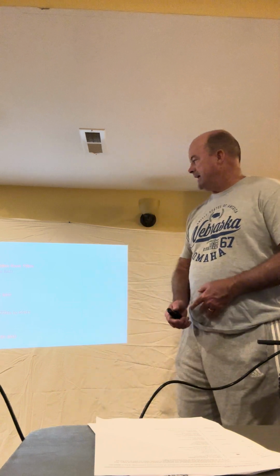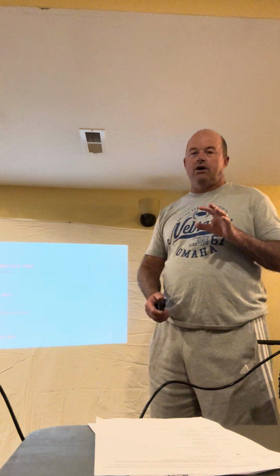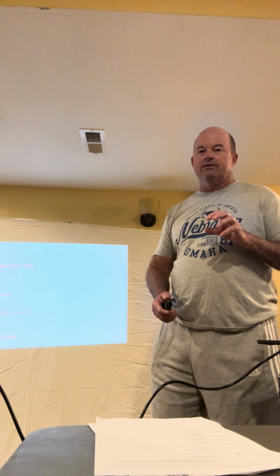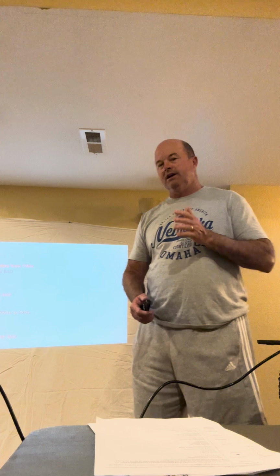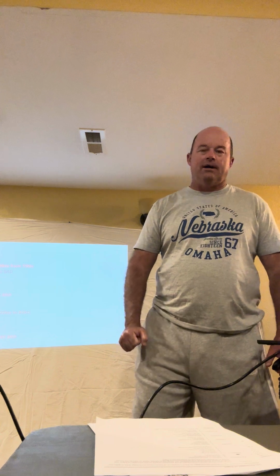When you come to land, if you get into a stall, right, it's very difficult. A lot of people die because they've got aft CG and they can't recover from a stall. It makes it much more difficult, right? It's kind of like a tail stall. So that's how you want to think about that.